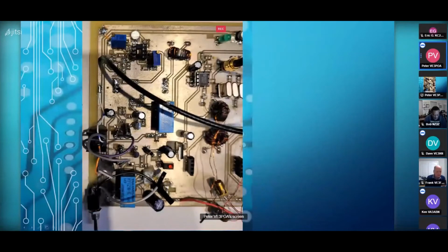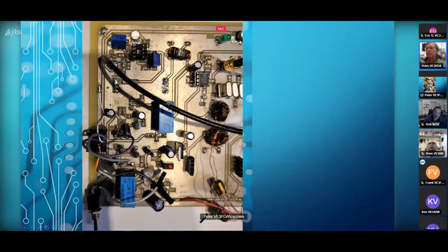Just decided to throw in the first version. This actually might be the second board that Dave and I did for the D612 project. 1253 lives up here. There's the 612 for going into the mix to the IF there. Some extra wires in here. I thought a good idea was hooking up to look at the crystal filter. I just wound a few turns around the toroid and fed that into the spectrum analyzer instead of tapping off and things like that. I know Dave did it differently, but I thought that had less effect on the circuit. Whether that's true or not, I don't know.